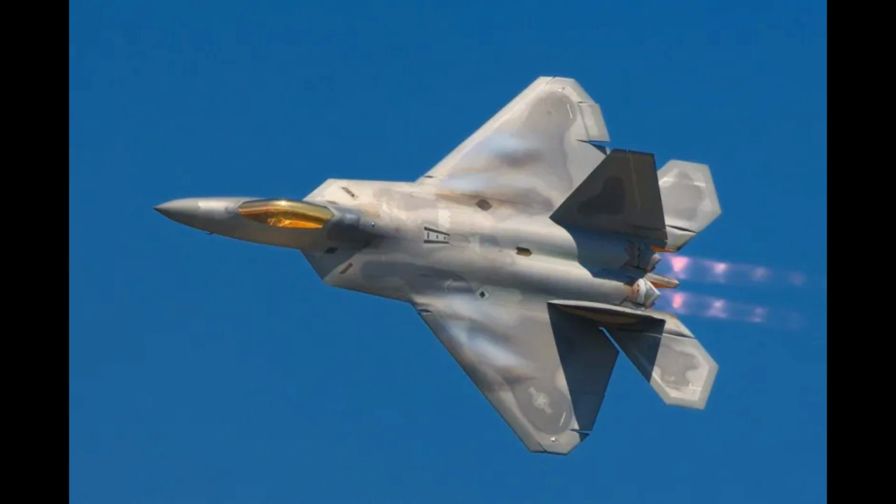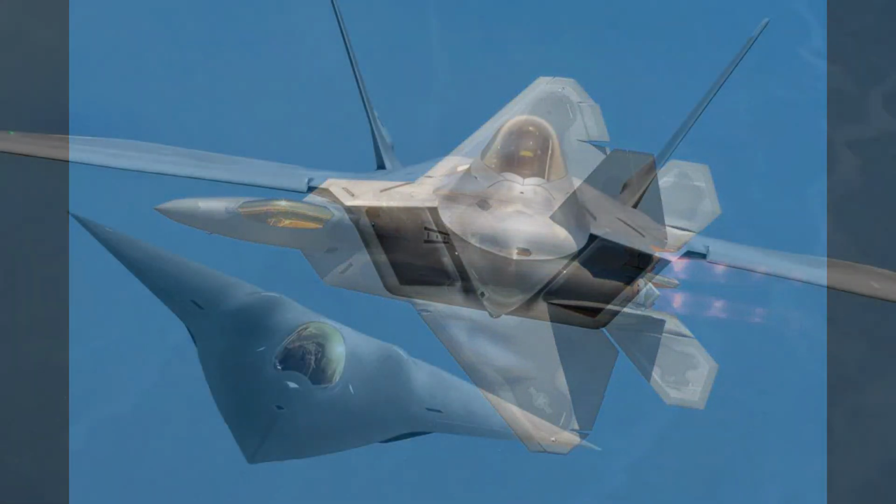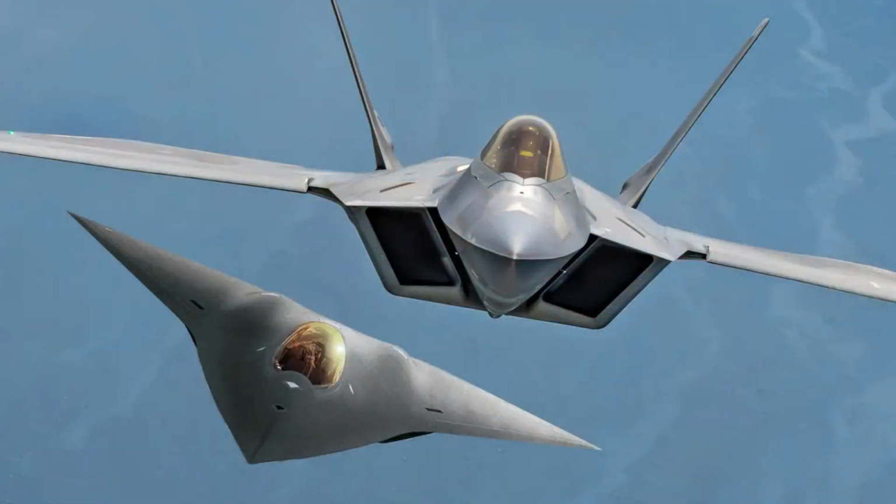Another advantage of composites is their good performance in a flexing environment, such as in helicopter rotor blades. Composites do not suffer from metal fatigue and crack growth as do metals. While it takes careful engineering, composite rotor blades can have considerably higher design lives than metal blades, and most new large helicopter designs have all composite blades, and in many cases, composite rotor hubs.